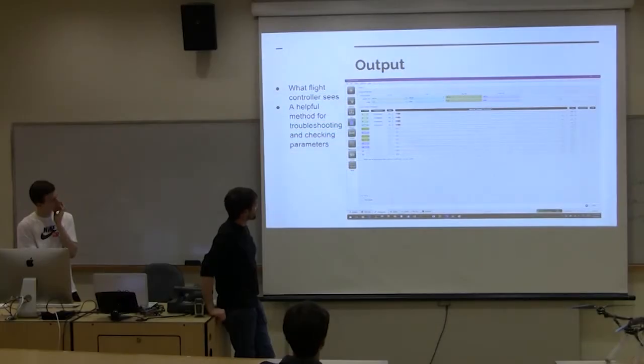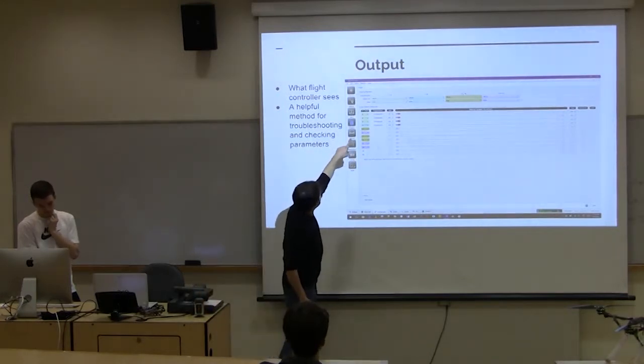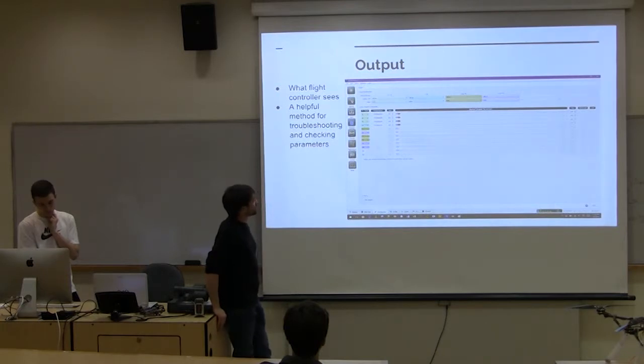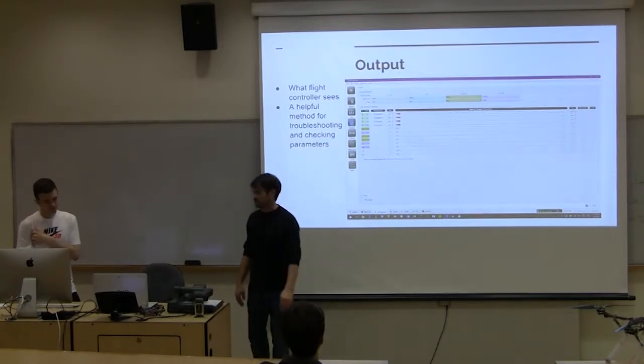So that's all you really need to do on that page. And then up here, the update, I can't really read what it says, but that refresh rate, I think it says 490 hertz. That's the one that you want to make sure is at least 400 for your flight controller. If it's down at 50, then you're not going to be flying anywhere. That's for the speed controller that we covered a couple weeks back.